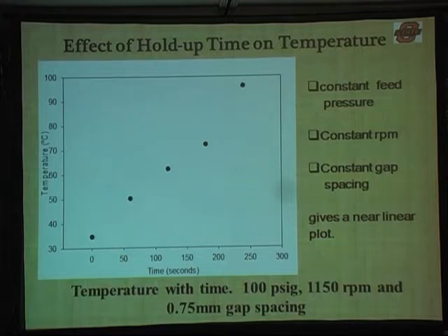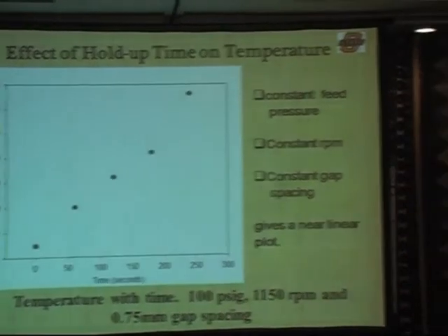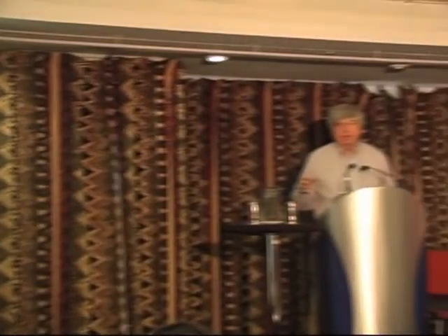So we're doing some experiments now so that the solid that's coming out is now going into an insulated chamber where the water can flash off and leave, and then we've got a drier solid left, and then we could potentially recycle that back to the inlet, and based on maintaining a value of torque in the motor, adjust the ratio of recycle to new feed.